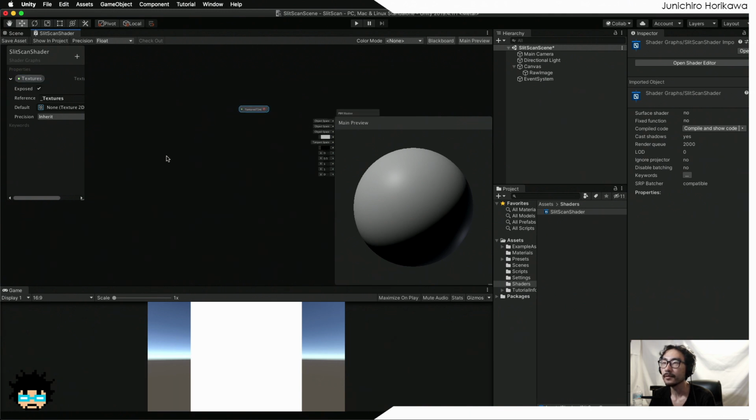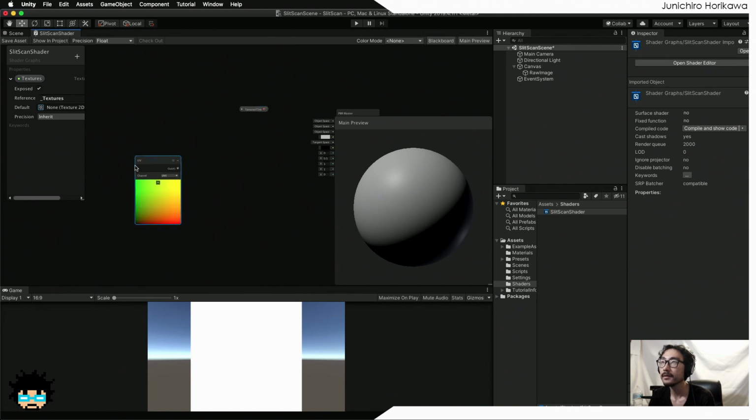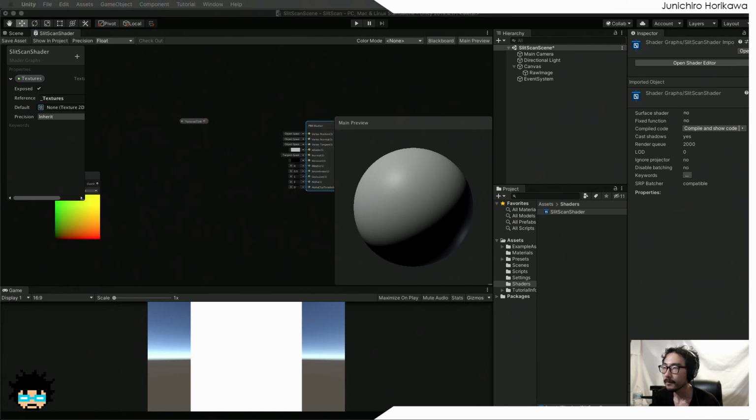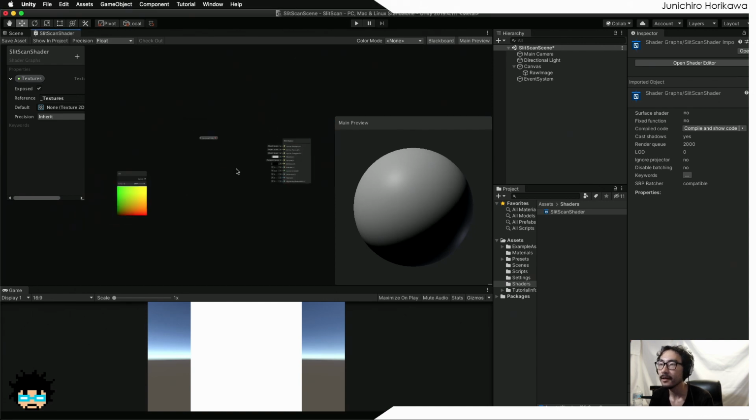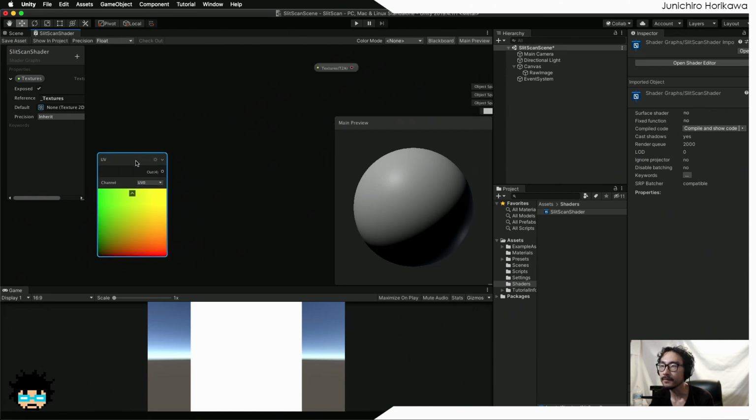We also need a UV in order to access the pixels on each texture. So create a UV. Alright, now what we want to do first is create a gradational map from black to white. It doesn't have to be horizontal or vertical gradation, could be any kind of grayscale image, but let's just create a grayscale gradation because that will be really simple to create from this UV.